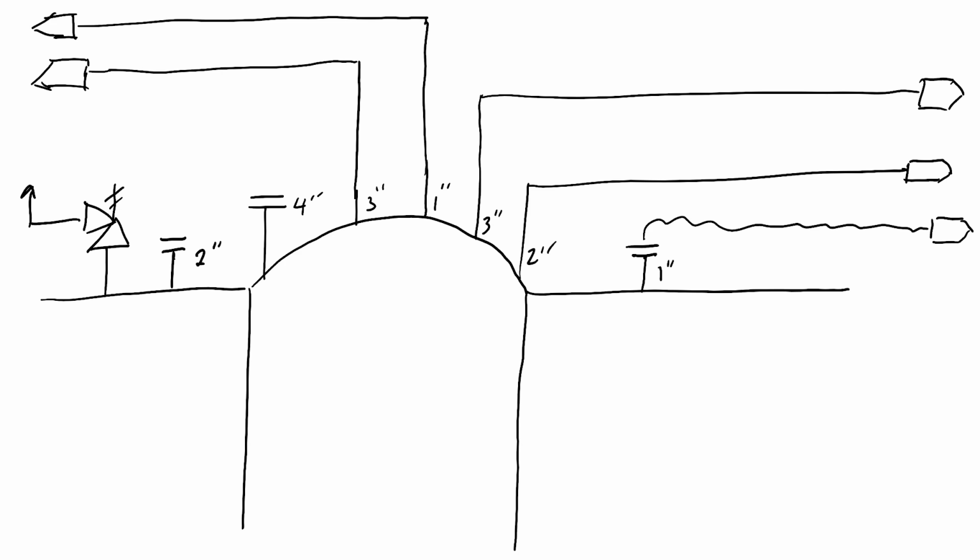You can see the piping's not crossing each other. Because this is a P&ID and not an ISO, that's completely adequate, that's acceptable for you to do. I actually encourage it. It's going to help you follow the lines a lot easier. And then also in terms of the arrangement on the tank itself, maybe the 4-inch manway is actually on the most right side, but it kind of made the drawing more complicated to look at.